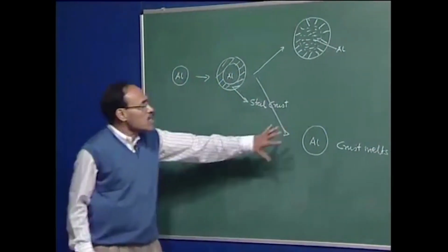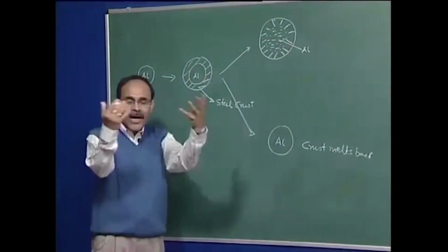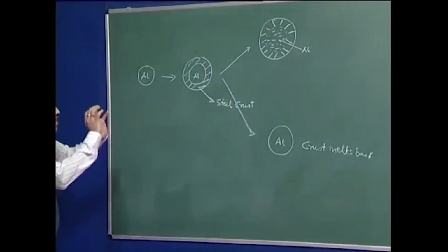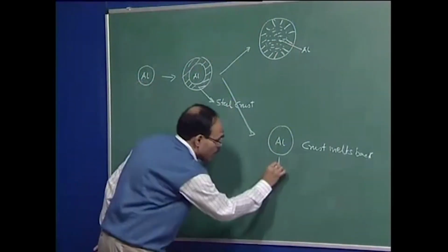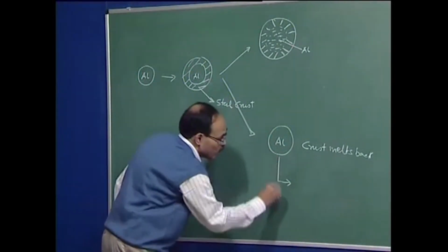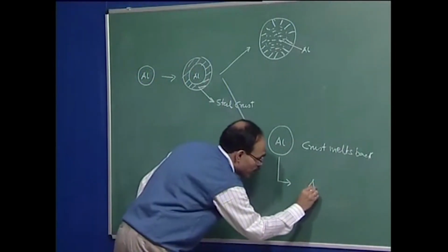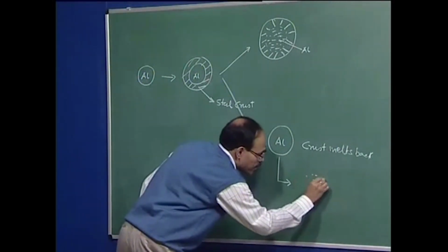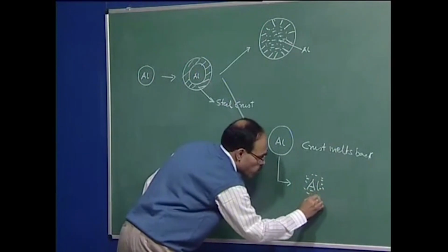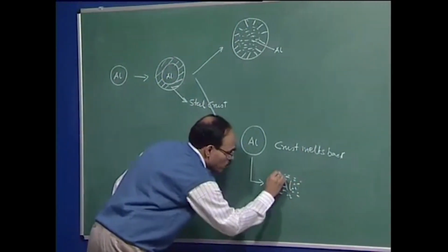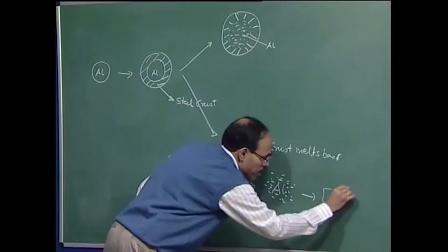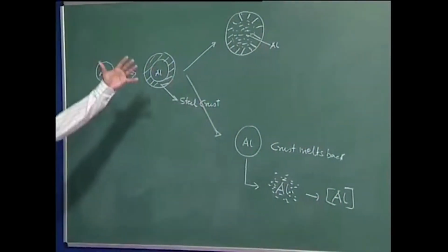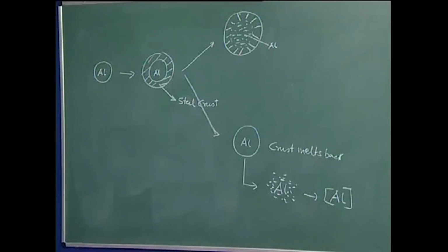These two possibilities will again depend on the bath superheat, etc. But in any case, the aluminum will become liquid aluminum again, and then it is going to go to aluminum in the dissolved state. So this is the way a solid projected into steel is going to behave.